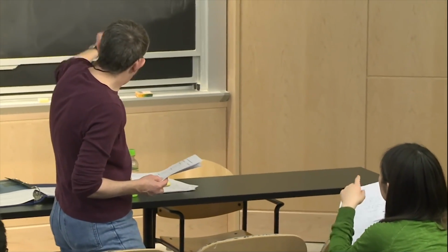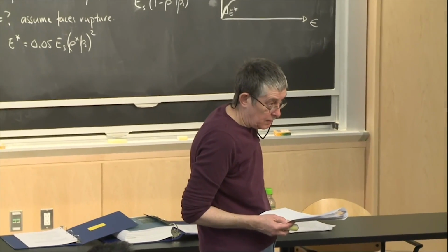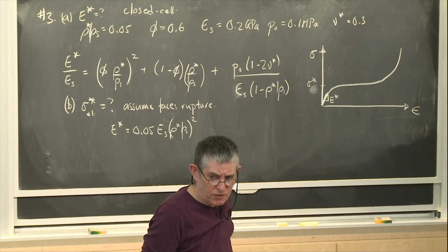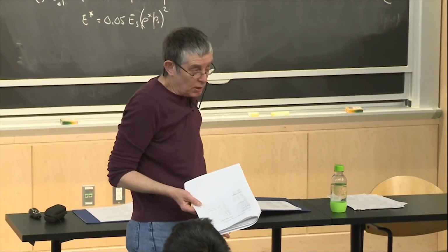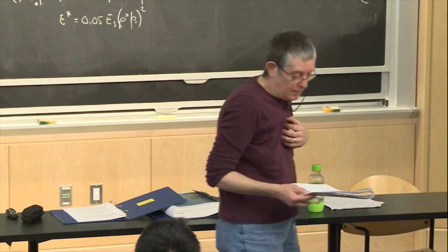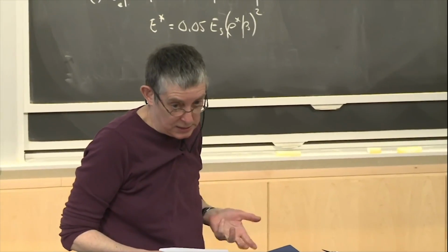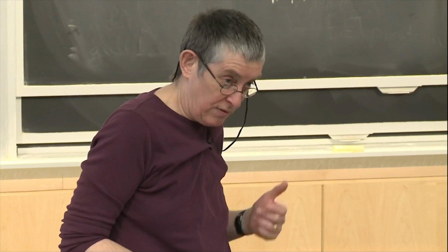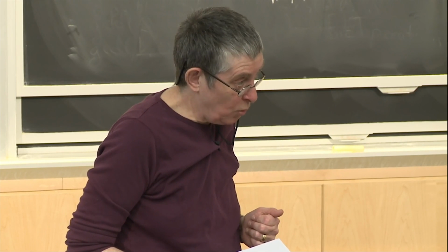But that is atmospheric pressure. So you don't need the gas term. Okay, yeah, you don't know that that's atmospheric. Do you ever do things in psi? No, you don't. When I was a student, a long time ago, the thing I remember learning was atmospheric pressure is 14.7 psi, more or less. And the conversion between megapascals and psi is about 145 psi to a megapascal. So the atmospheric pressure is about 0.1 megapascals.